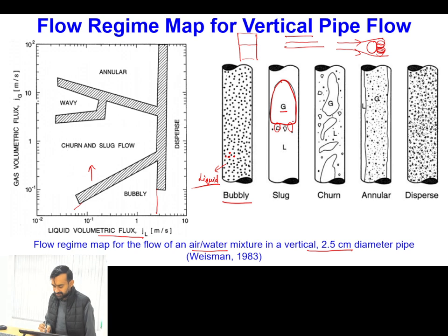These recirculating structures will lead to the occurrence of a dynamic interface at this point, and from this, interfacial waves will be there. If the amplitude of any wave is growing, that will lead to formation of one small bubble at the wake of this bigger bubble. The small bubbles which are traveling behind this are called satellite bubbles.